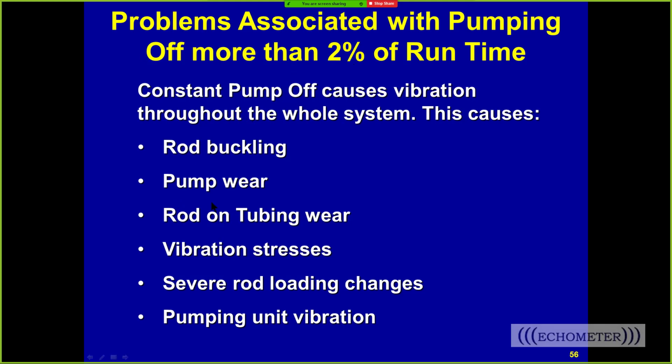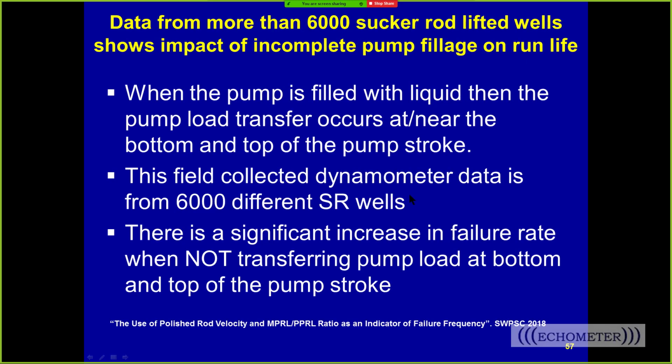You have rod buckling, pump wear, rod and tubing wear, vibration stresses, and severe load changes. You have pumping vibrations, and this is caused by excessive strokes with incomplete pump fillage. This is a paper that talks about that. It's a paper that I was a co-author on with Steve Galt from Oxy.